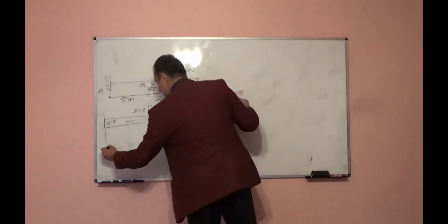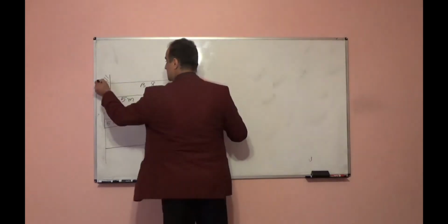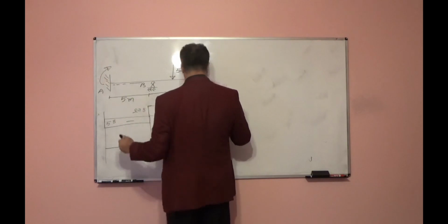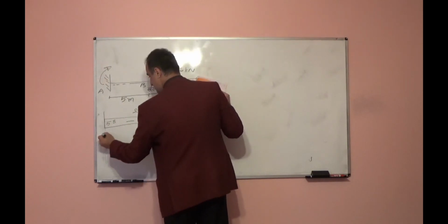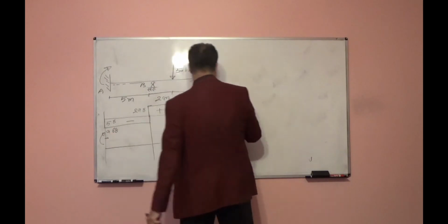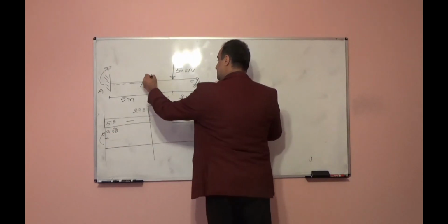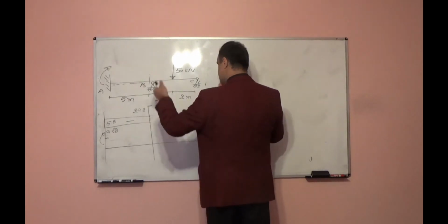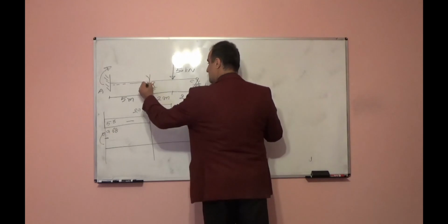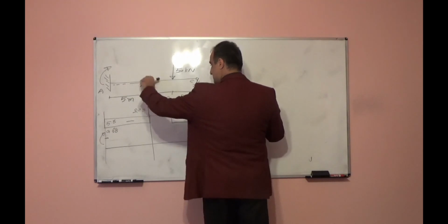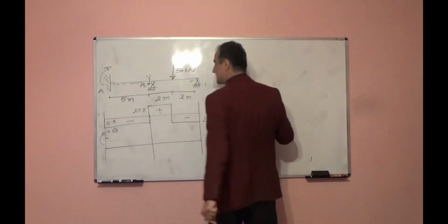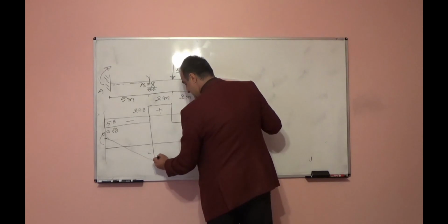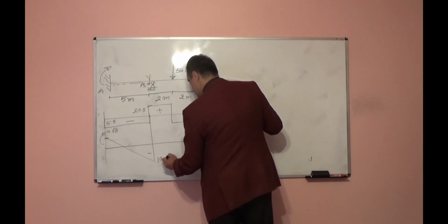Bending moment diagram. Moment here is clockwise. If you apply moment clockwise here, it creates tension underneath. So positive 9.68. Moment on this side is counterclockwise. Moment at BA is again clockwise. If you rotate point A on the left side clockwise, it creates compression underneath the beam, so it is negative moment. So it comes from positive to negative 19.35.